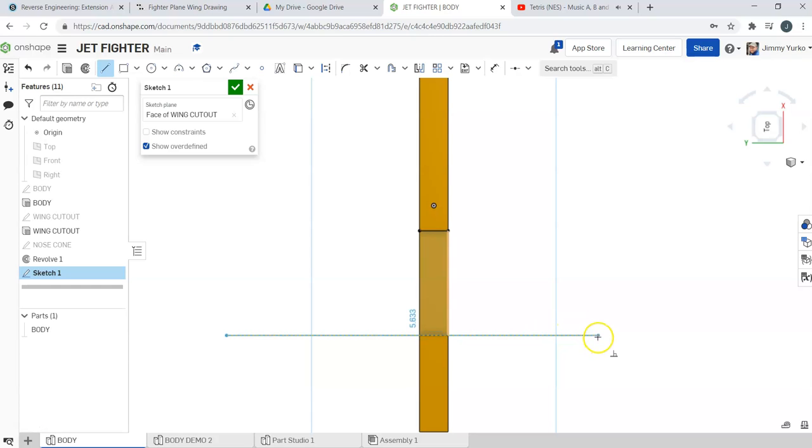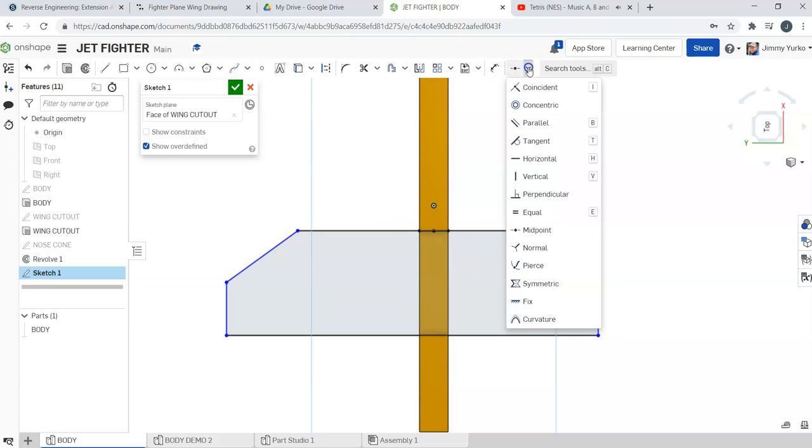The beauty of CAD modeling. Control Z. Anything you don't like, just undo it. In fact, let's go ahead and do this as 2 segments. I'm going to go to that midpoint, and then a segment. Even though that may look funny, like, what difference does it make? Well, instead of this top section being 1 line, it's now 2 lines. And that means that I can set those to be equal to each other.